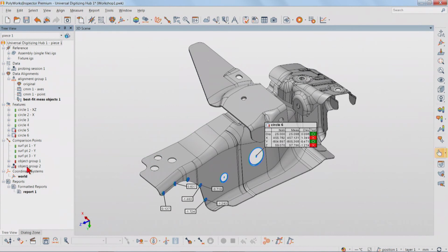Now, this is where the quality manager comes at me and tells me, fine, okay, we have inspected those pieces, we have our inspection reports, including control views, and now he asks me, from now on, we'd like to make sure we measure the thickness of all those sheet metal components in this assembly. The problem with that, I could find a fancy way of doing this with the CNC CMM, but you probably know that this might not be the most efficient way of making the measurement. In other words, maybe a good old micrometer would do the job to measure those thicknesses.